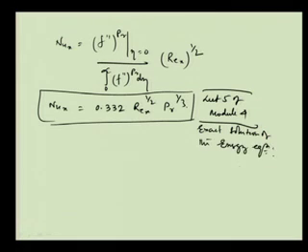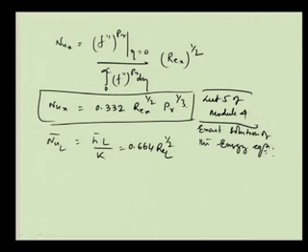Now, if we try to see that average Nusselt number, it becomes h average L by k. So, the average Nusselt number based on the average heat transfer coefficient for the overall plate becomes 0.664 Re_L^(1/2), based on the Reynolds number based on the length, times Prandtl to the power 1/3. So, this part we have already discussed.